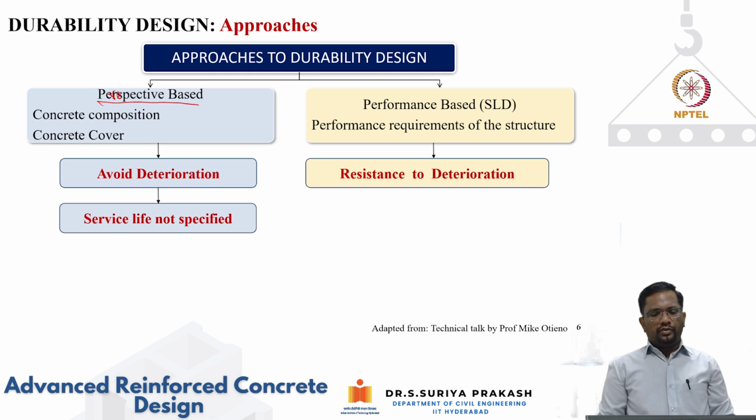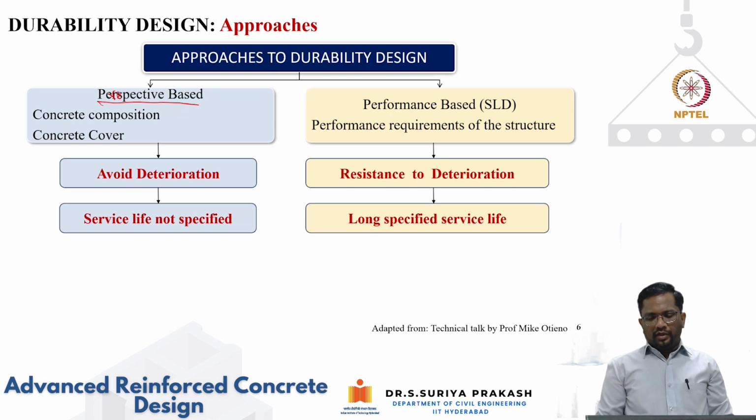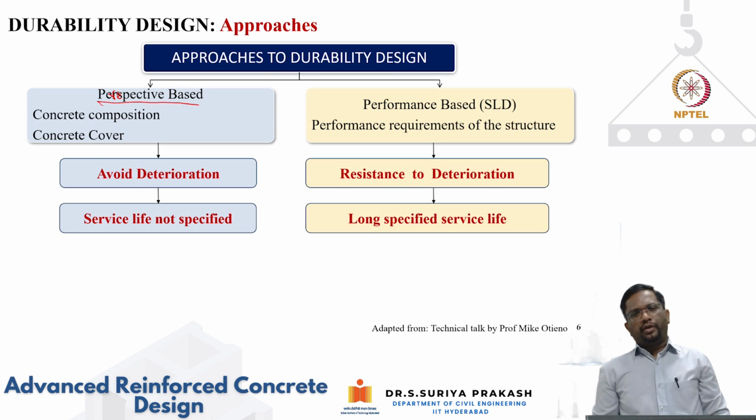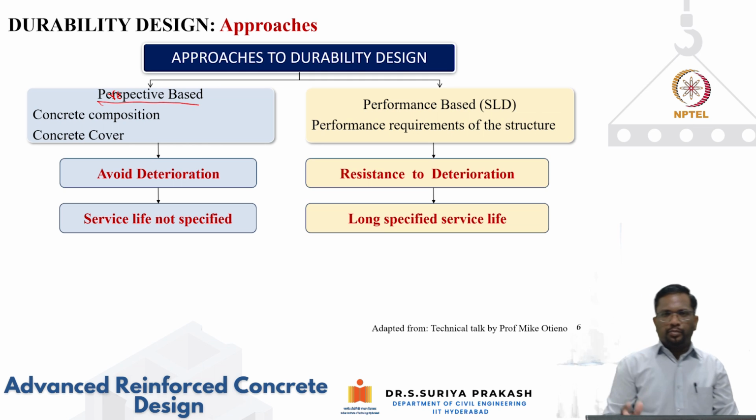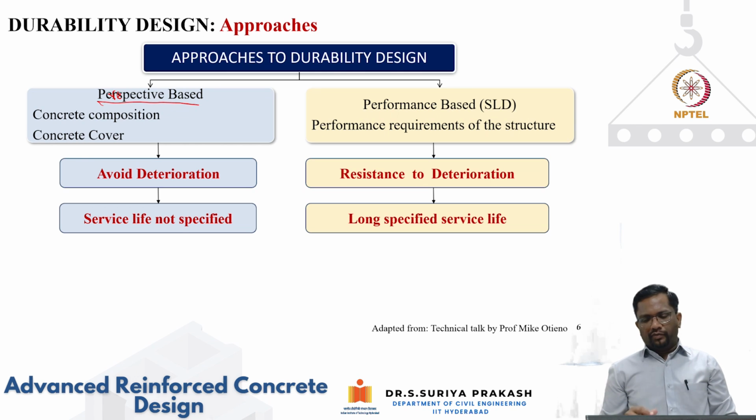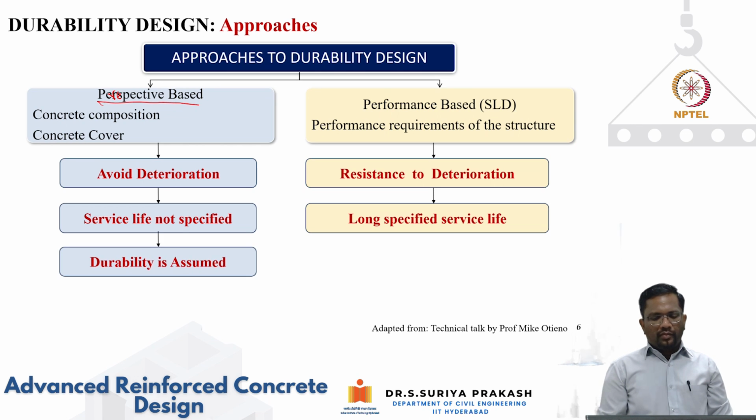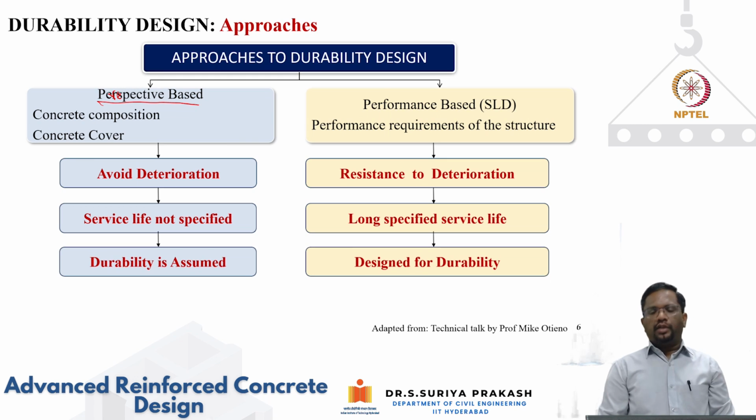If you follow all of the prescriptions, then your structure is deemed to satisfy the durability requirements. But here you are specifying a particular service life, and for that particular time you are also guaranteed an acceptable level of deterioration. In the prescriptive approach durability is assumed, and here we are designing for durability.